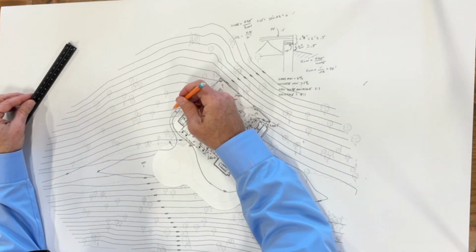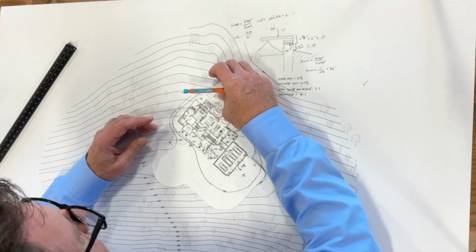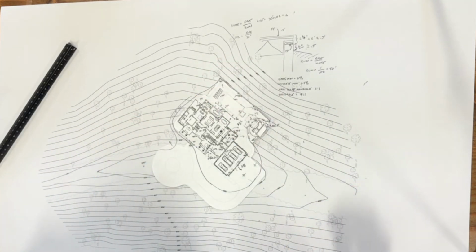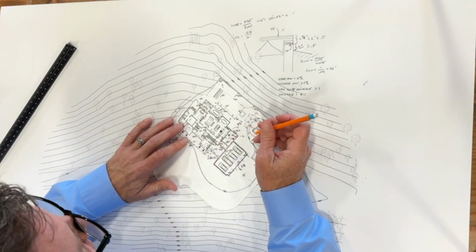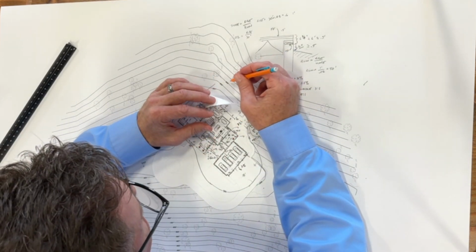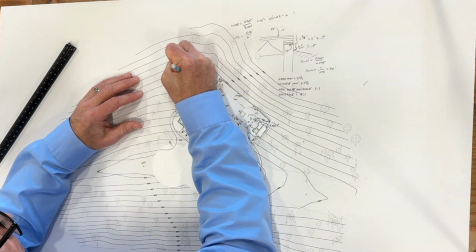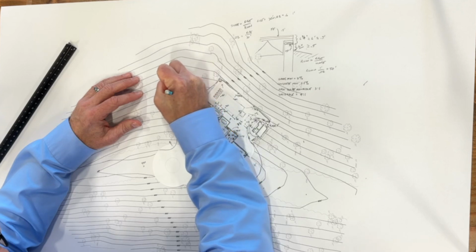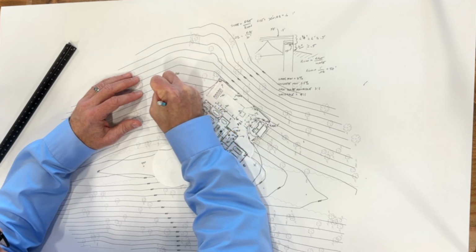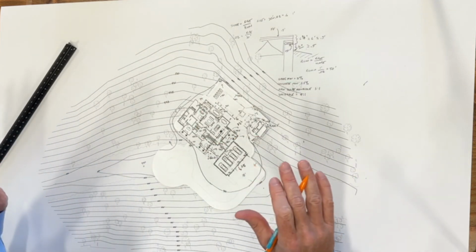But if you look at this, that contour, oh, you can't really see it. And this is, by the way, where you should kind of rewrite all the elevations as you start doing this: 928, 929, 930. So I know that this is a 930. This makes this a 931, 932. This should look messy. A good site plan should look horribly messy by the end.